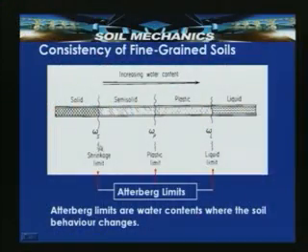Here, the consistency of fine grained soils is given. The limiting water content at the interface between the solid state and semi-solid state is termed the shrinkage limit. The limiting water content between the semi-solid state and plastic state is the plastic limit, and between the plastic state and liquid state is the liquid limit. These liquid limit, plastic limit and shrinkage limit are known as Atterberg limits.